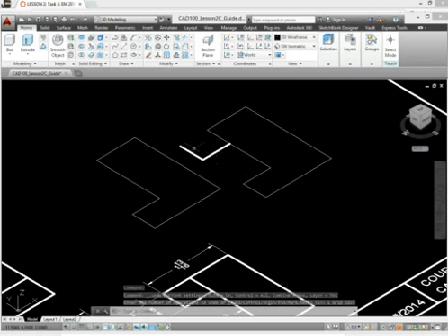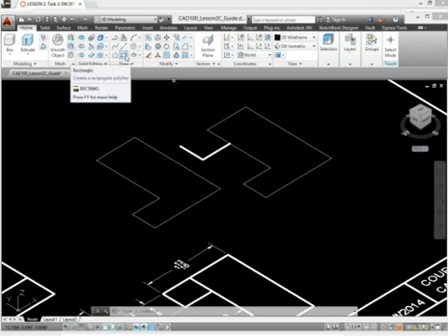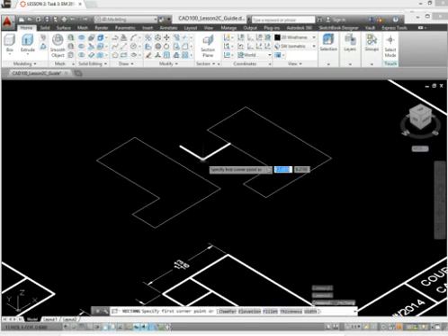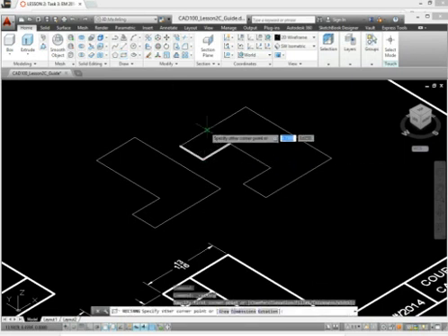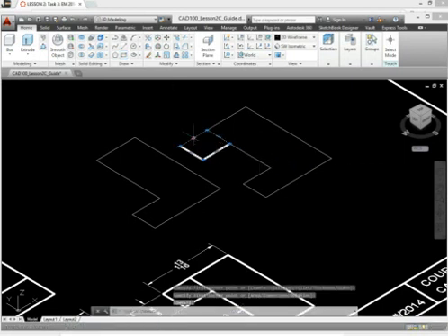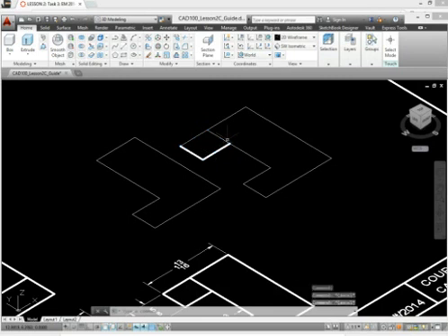Well, we do need another region right here, so we might as well draw something that we're going to need. Let's do a rectangle to save some time. You can pick this lower left corner here and grab the opposite right corner, and now we have a rectangle which is also a type of polyline and already a region in itself. So we have our two regions, and now we could extrude.